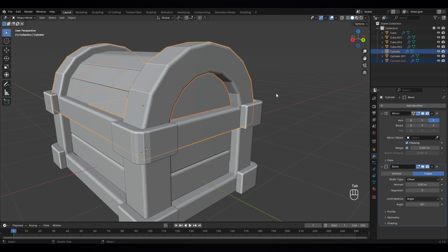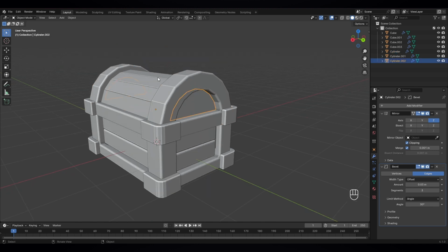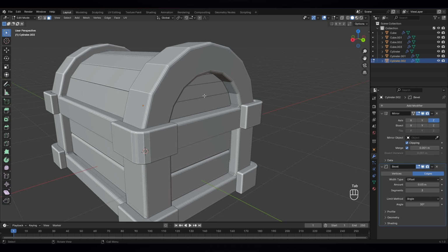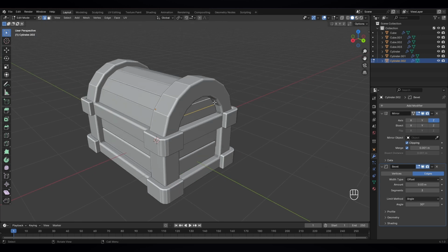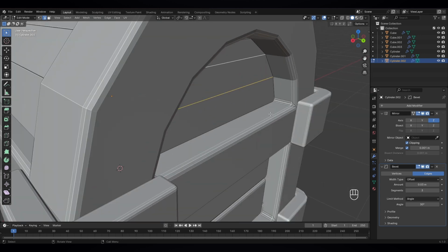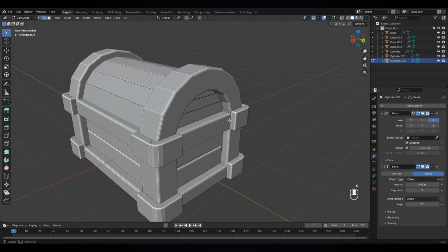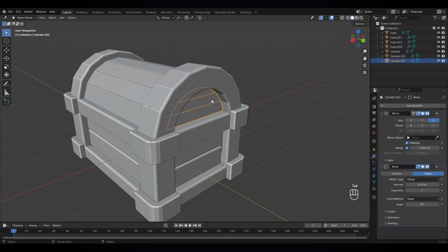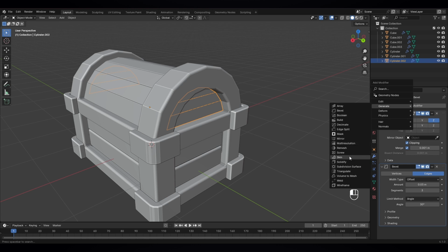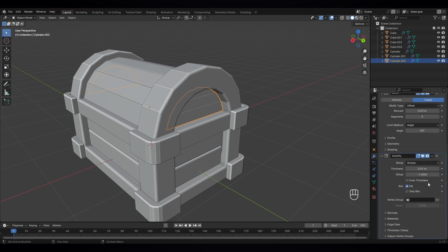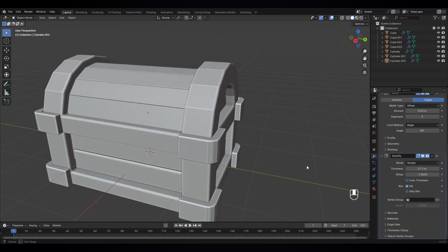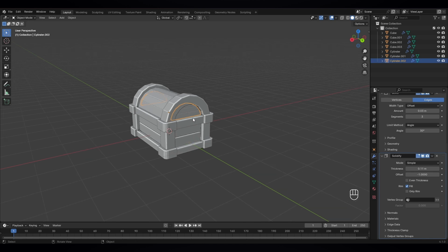Okay, go to object mode by pressing Tab and select this, and go to edit mode by pressing Tab, and this time I want to select, okay, let's select 2, and again Ctrl B to bevel, tap X to delete the faces, and go to object mode and select it, and let's give it a solidify modifier too, and increase by 11. I think that looks nice.